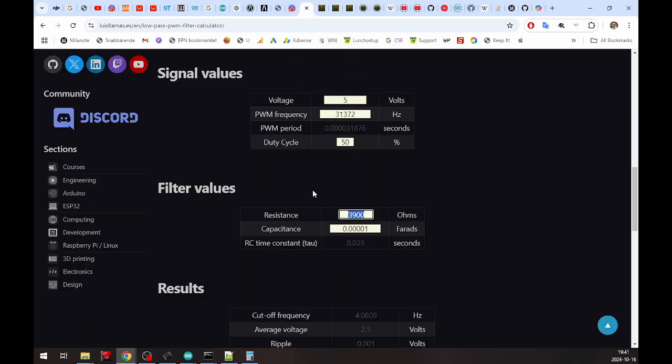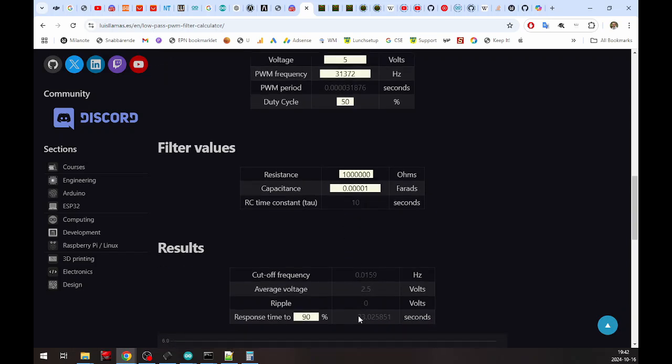So I started thinking that, well, then you have a 1 mega ohm resistor, and you have the same capacitance because it's just one capacitor. Then the tau will be 10 seconds or 23 seconds before we're up to 90%. And let me tell you, that is not the fastest ADSR in the world. I was thinking too long about this one without asking anyone.